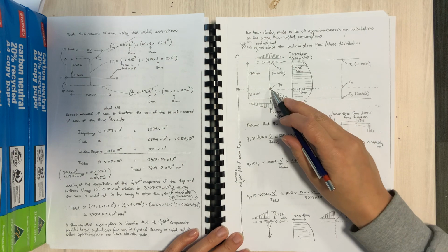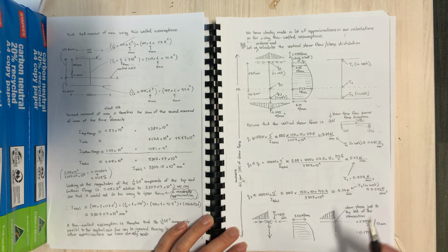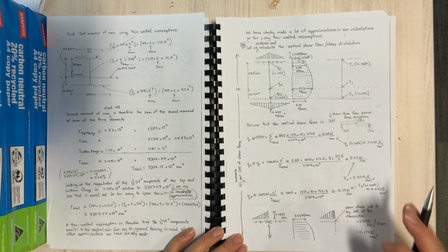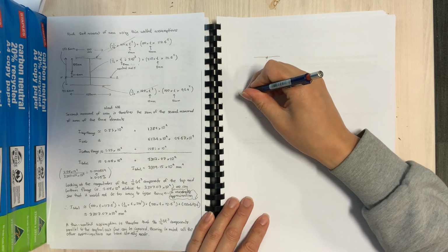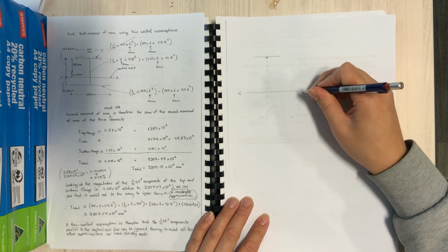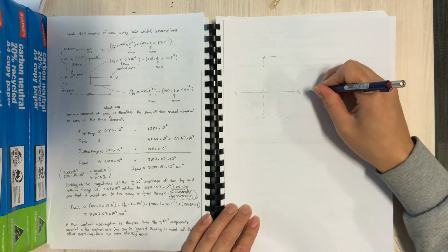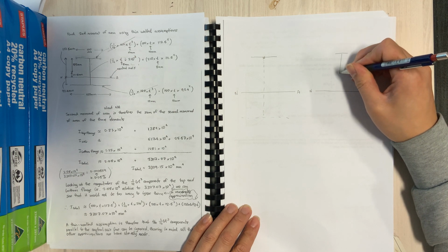Q2, so we know that the neutral axis is the position where the shear stress will be largest, and therefore the shear flow. So that would be the neutral axis. So a longer way to do it might be, let's work out that section there.